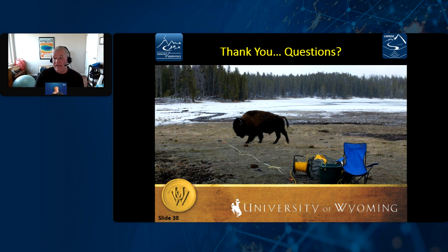And so to get useful information out of a well that's not drilled very deep, because they really avoid drilling through that bottom clay. They don't want to do that. They don't want to provide water pathways out of the formation. So they only drill into the sand, and as soon as they get to that bottom clay, they stop. And so that isn't very good for the length of most normal resistivity tools. And therefore it's a little tricky. And so they get around that problem by flooding it.